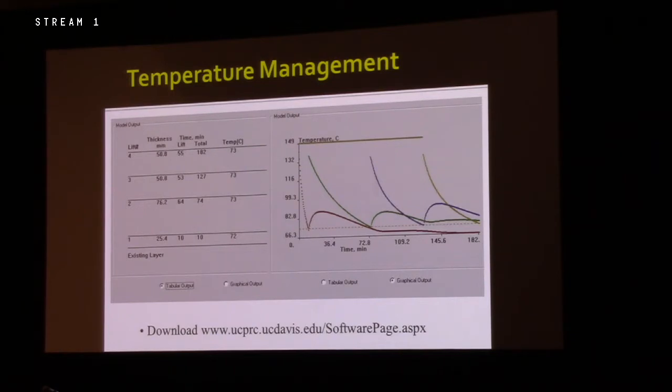One of the great things about this, especially as we know with temperature and asphalt mix, is that when you're in a full closure 55-hour operation, you're paving in the morning, noon, and night. And as we know, the temperatures will definitely change. We need to be on top of what that looks like and what effect that's going to have on the paving operations. So understanding the time to compact of mixes will help us understand how much material we can actually get down during this long shift.